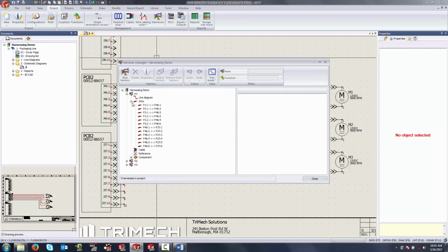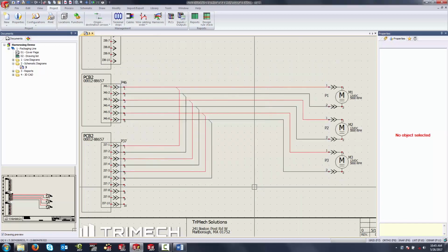And you can see within here, all of the wires and components, back shells and connectors get added to the harness itself. So later on, we can run a bill of materials to keep track of all the information within there. So we've just finished documenting this design by reusing some circuit information through the use of macros and by numbering all of our wires automatically. So let's go ahead and see how we can now produce associated documentation like bills of materials and wire run lists using some of those tools in SOLIDWORKS Electrical.